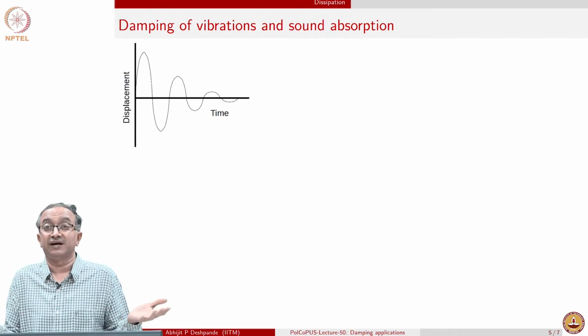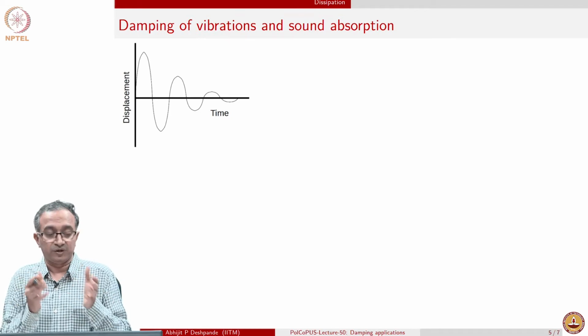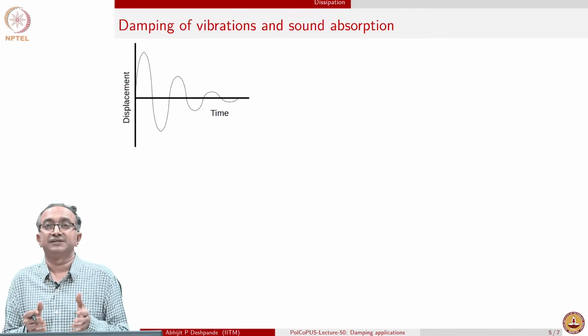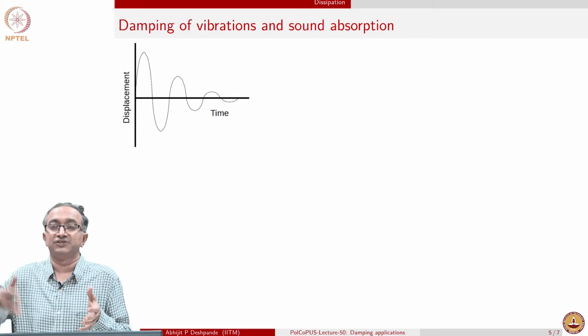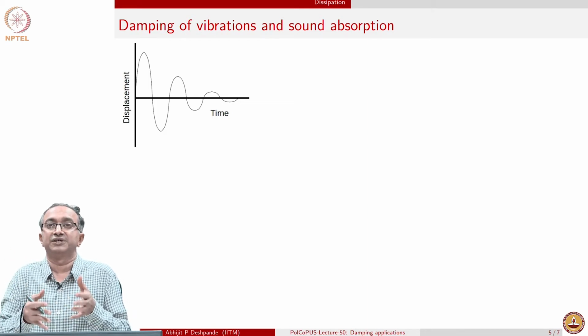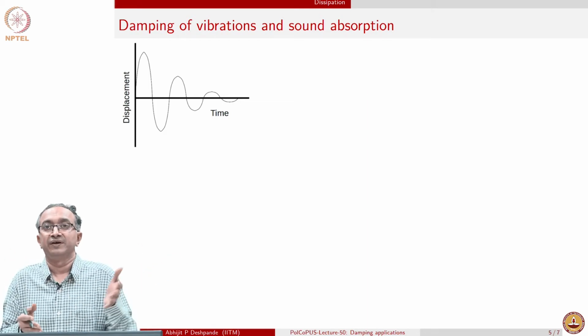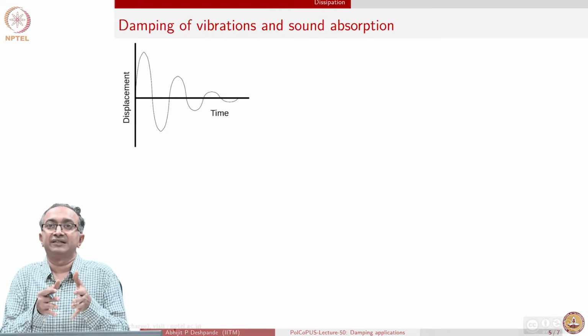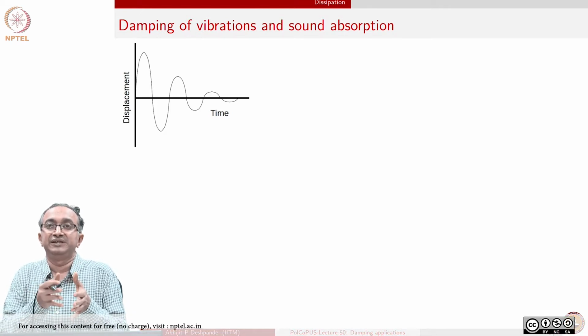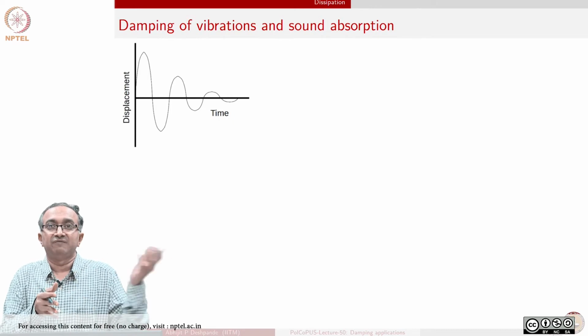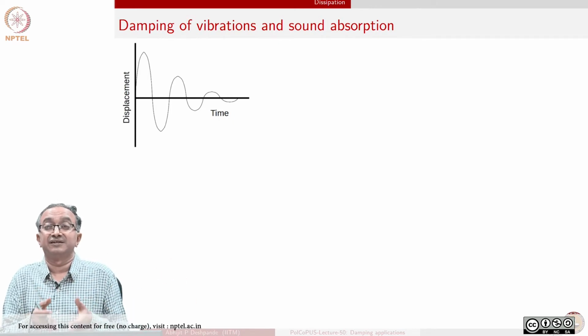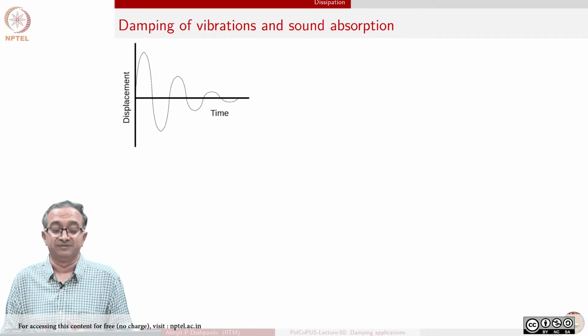So, therefore, again we vibration isolate. What this vibration isolation device does is it takes the mechanical energy due to vibration on one side and absorbs it and does not transmit it. If you have a perfectly elastic material, then whatever vibration is being felt by this material will get transmitted to the other side and it will not dissipate any energy.